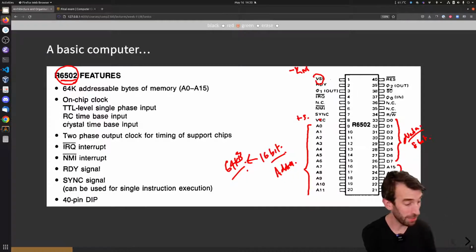So my question was, how much memory is addressed by the microbit? Someone said a few hundred megabits. No, I don't think so. The microbit has a 32-bit address bus. It also has 32-bit registers, so they're the same now. And that means that it can address 4 gigabytes of potential memory. It doesn't have all of that memory wired in, but it has the capacity for it to be there. Yeah, so now, where are we? The 6502 has this 64 kilobyte possible address range.